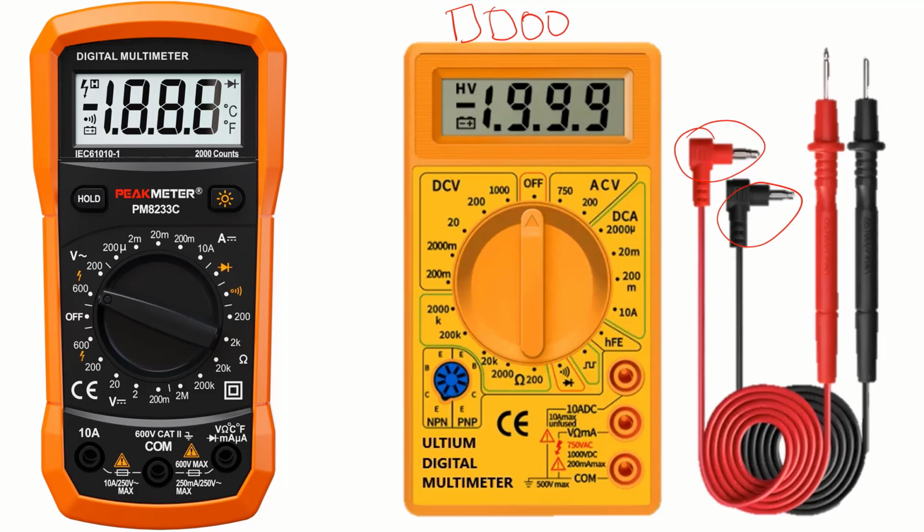This also gives you the precision, but the value on the screen is not a reliable one. When you turn to a given port, the value you see appearing here, 000, is the precision of that particular scale of measurement. When a multimeter is given to you, the first thing you do is verify if it is functional, and to verify that, it suffices to test for continuity.